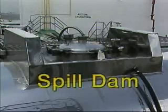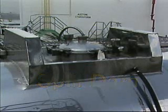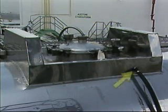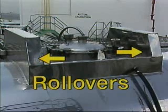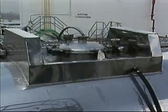Tank trucks also have a spill dam around the manway cover to hold any spilled product. If a spill occurs, it should be cleaned up promptly. On this truck, spills can be removed for safe disposal through a drain hose. Components called rollovers are built into the front and back ends of the spill dam. They help prevent the tank from being punctured and the valves and vents in the manway cover from being damaged if the truck rolls over.